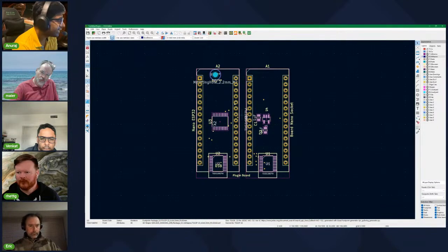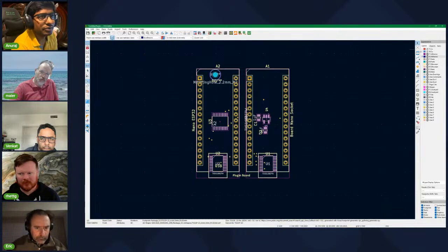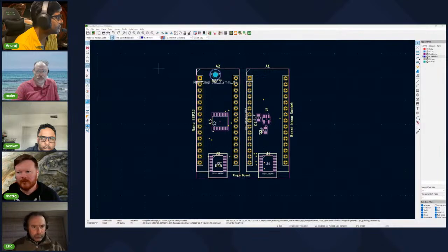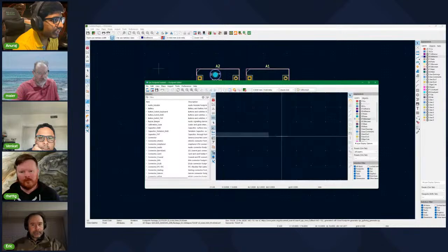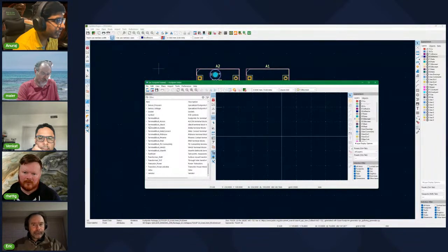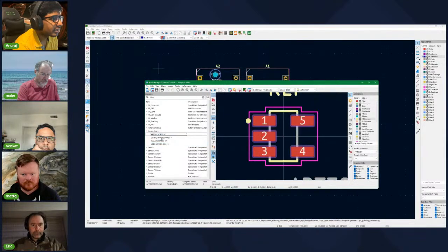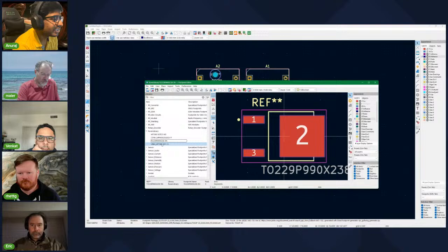So you can also create this footprint. If you go to this footprint editor, let's say you don't have any component inside, you can also create your own footprint. I had tried a few components, and then you can create your own library of footprints. That's for if they don't have the thing that you want. So I created some libraries.